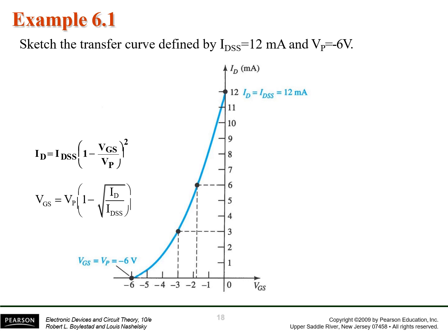Now, in case we put a value of minus 3 volts in place of VGS, we get a value of ID equal to 3 milliamperes also. So again, we can plot another point. Now we have got 4 different points. We can join these points to form a curve. This is the characteristic curve, or the transfer curve, of a particular FET.